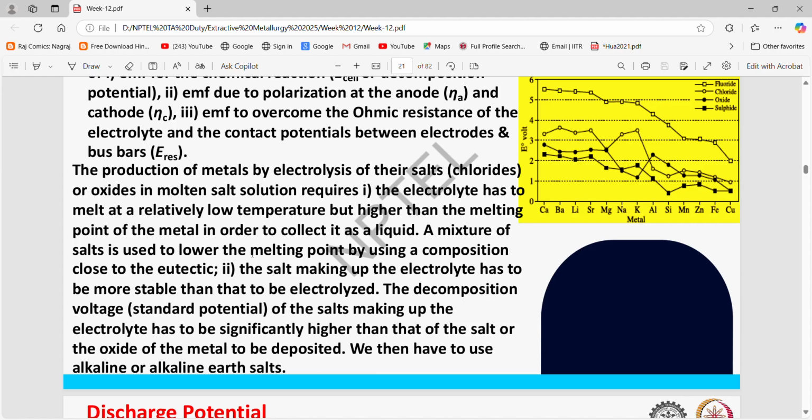For example, when we talk about gold refining, we generally go with electrolysis refining at room temperature, using electrolytic solutions made by adding some metallic ions in an acidic or basic solution.